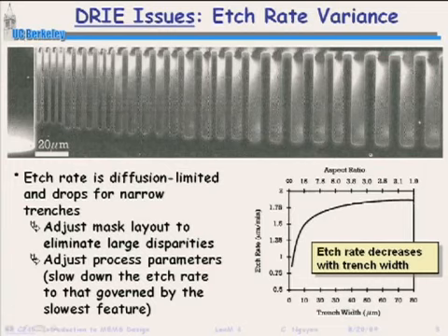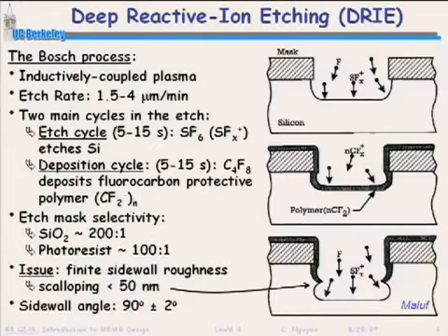Okay, do you have a question? Oh, I'm sorry. So silicon, so in these, I didn't even talk about these, did I? So the silicon dioxide, when it says 200 to 1, that means it's etching silicon 200 to 1 oxide. Which means this etch doesn't attack oxide at all, almost. And we'll see that there's a consequence to that very soon when we start talking about MEMS.